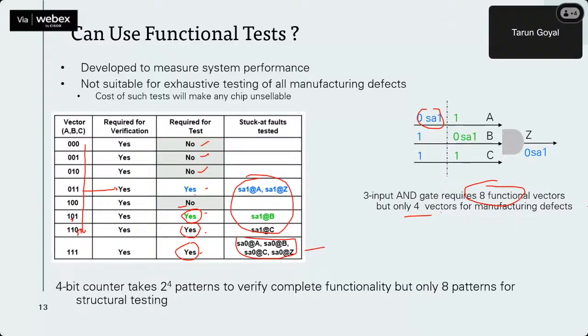Yes, why do we need functional test? To ensure that this AND gate is working correctly. And like that, there is a device. All those performance parameters and all correctness can be tried on only one die, to ensure that with a couple of dies we are meeting the functional requirements. But we are not testing every manufactured die with these eight patterns, to avoid increasing our test cost.